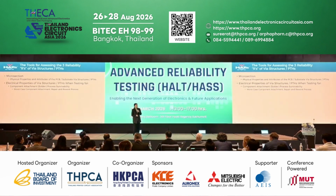When we test solderability and survivability, we need to also count the repair and the rework. Most of the time, the repair and the rework temperature is higher than the typical temperatures inside the reflow oven or wave soldering oven. So in the survivability test, we need to count not just the cycle quantities, but also the temperatures in the worst cases.